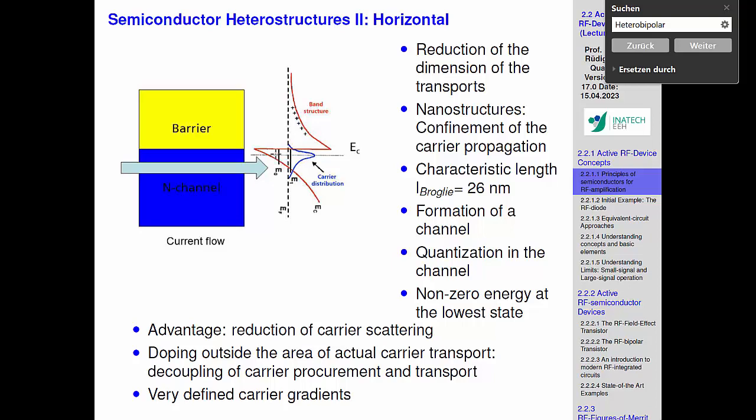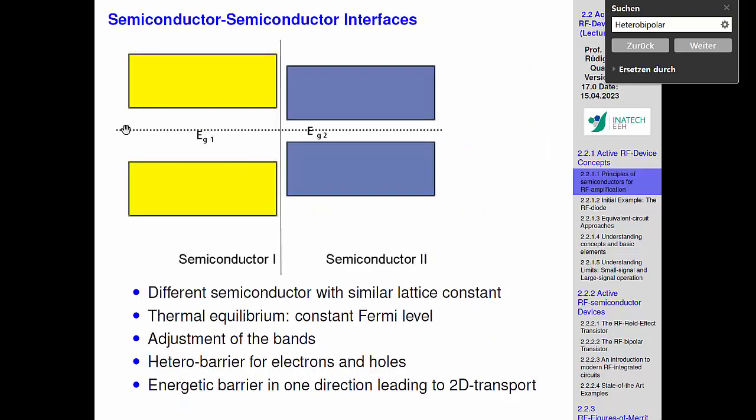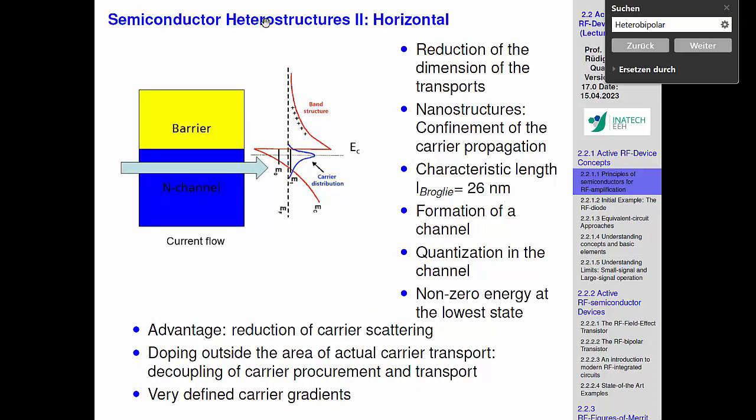Typically, when semiconductors are undoped, it's somewhere in the center, and it is also the guiding principle for the adjustment. So they have to be equal on both sides, because there can only be one level of water in the crystal, so to say. This is where the electrons are. So you see, because they have to be equal, this bending occurs.